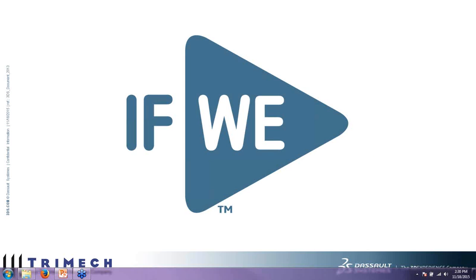All right, looks like Guillermo has a question. He is wondering, how is the migration from WPDM 2015 to PDM Standard 2016? That's a loaded question. Mostly I say that because with Workgroup PDM, if you have been using Workgroup PDM for a very long time and you've set up multiple different revisions, multiple different life cycles, and you've changed them over the years, the migration might be a little bit more difficult for you than for someone who's been consistent with their revision schemes and their life cycles.